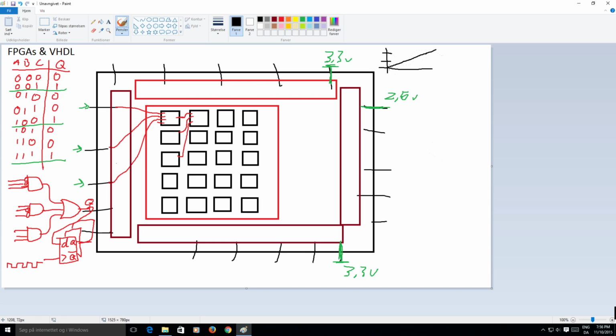If you get up to very high speed signals, and say this is 3.3 volts, the output of the transmitting end has to swing quite a lot. And if you have inductance and capacitance on the way, a perfectly fine square wave on the output of something might not be perfectly square wave when it reaches the other end. So usually the lower your signal is, the less it has to move. But lowering the voltage won't help with the noise, of course. So most FPGAs will also do differential inputs and outputs, where you don't use one pin, but 2 pins for each input and output.